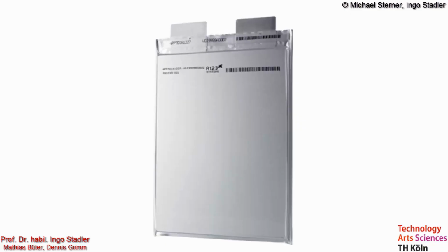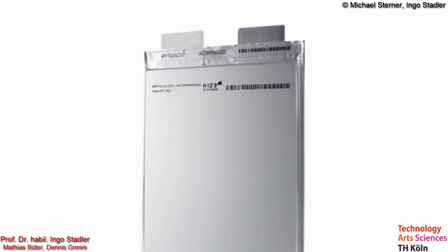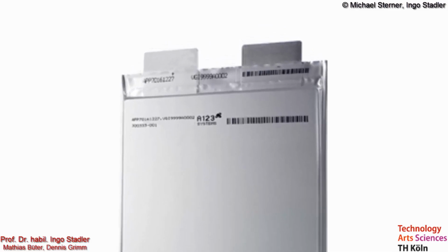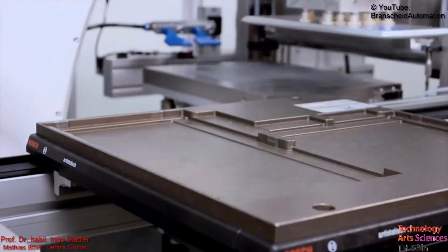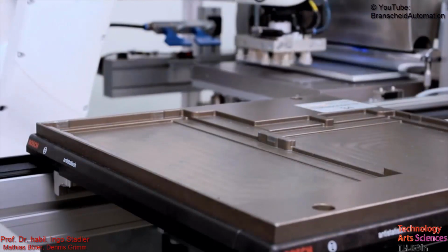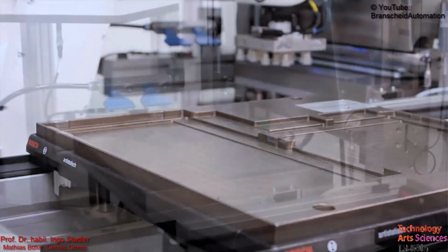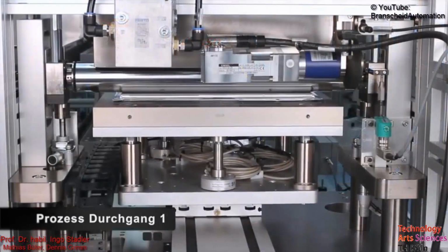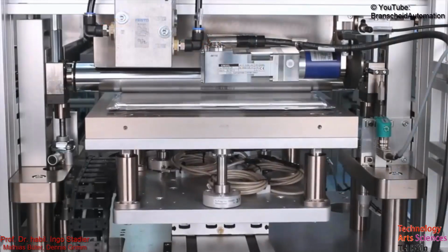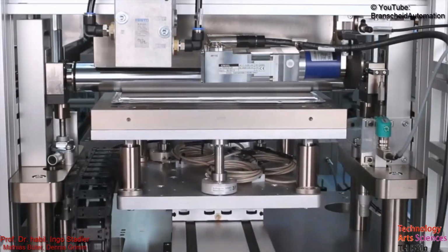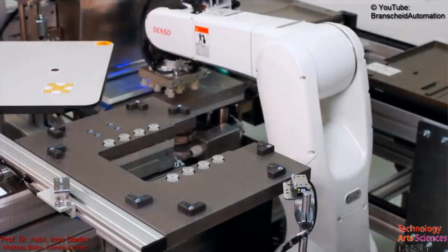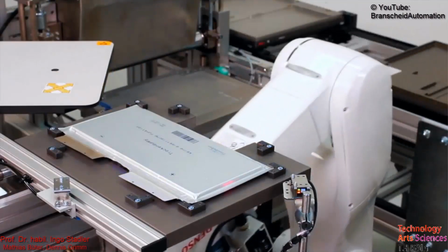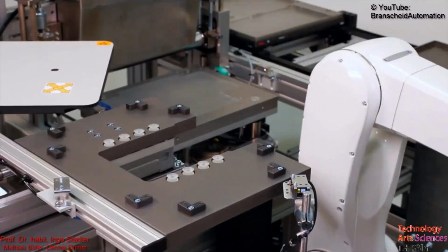First, the pouch cell. It is also named coffee bag cell, as it is welded in a vacuum with an aluminum foil similar to a package of coffee. This type is applied in electronic devices as consumer applications like smartphones and laptops, and is also increasingly applied within e-cars. Due to the low weight of the housing, bigger energy densities can be achieved. A disadvantage is that this type has safety problems due to its flexible and not so stable housing.